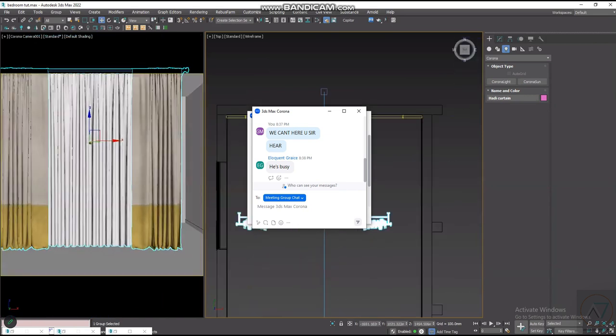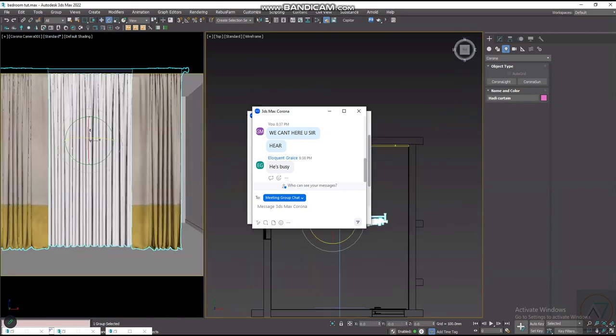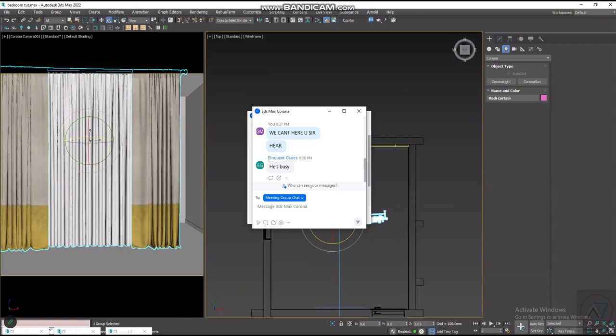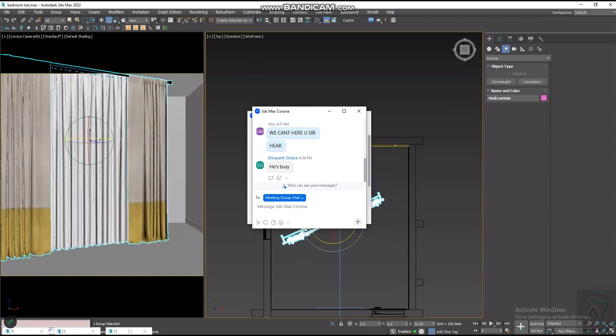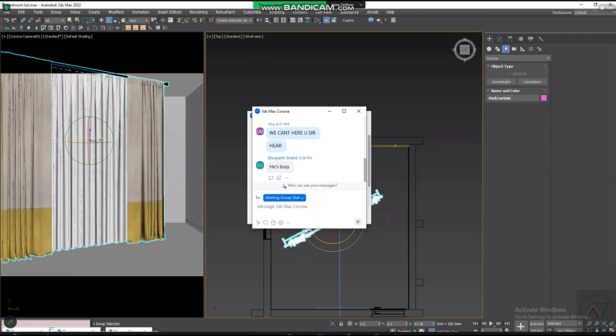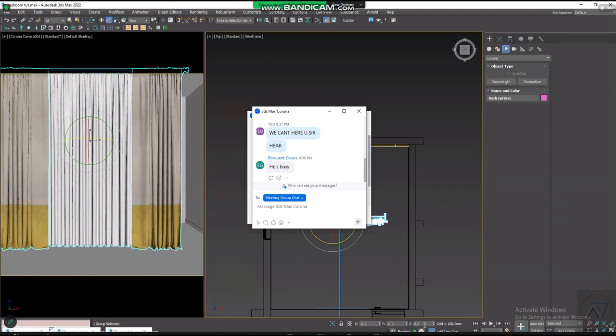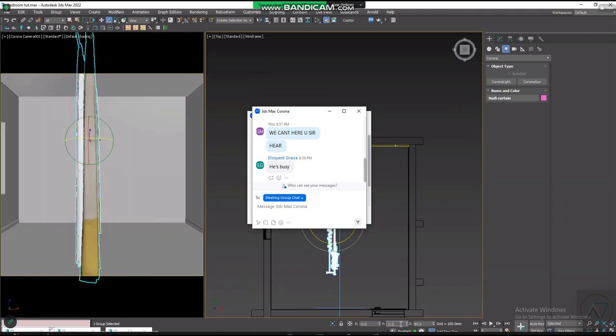To rotate, the shortcut is E, or you click on this one here to rotate. If you notice, when we are rotating, it's giving us a bunch of random digits like 5.8, and I don't want this. You can actually rotate from here and just set it to 90. To be fair, I don't really use this one here.